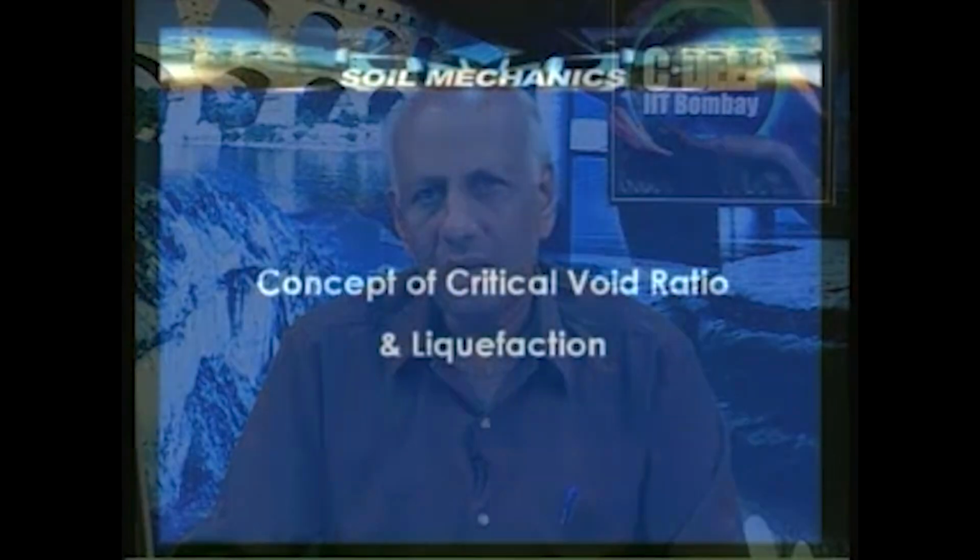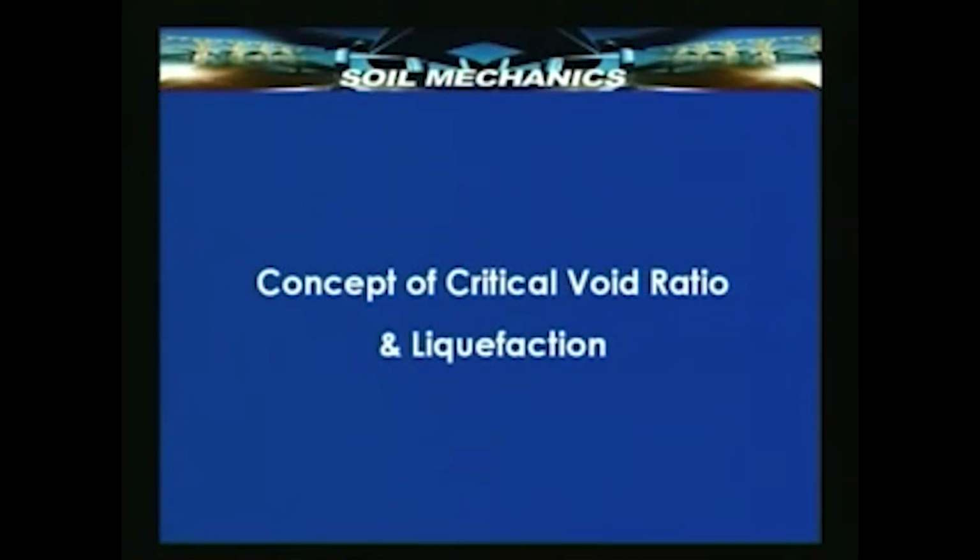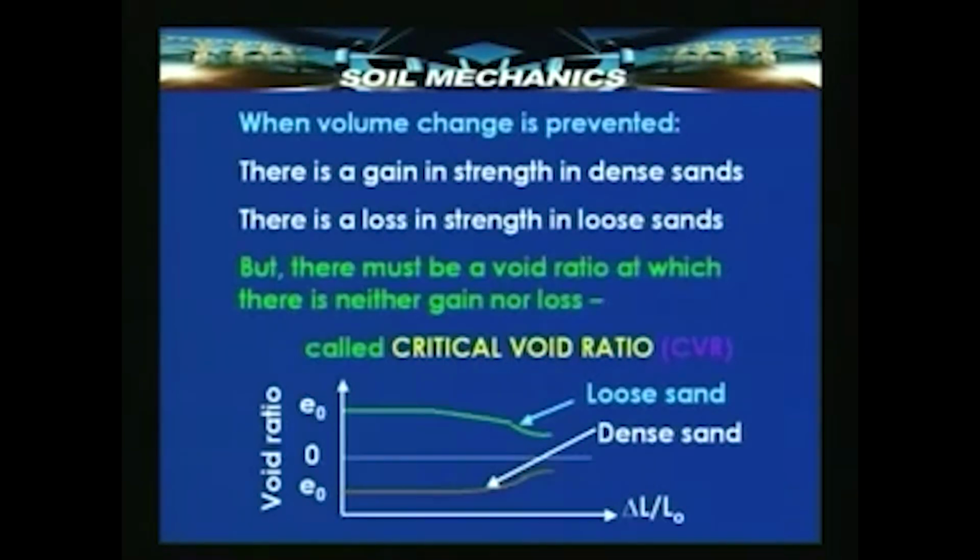Now let us take a look at the concept of critical void ratio, the meaning and significance of liquefaction, and how to determine it. When volume change is prevented, there is a gain in strength in the dense sands, because as we have seen in the behavior of the dense sand, there is a compression initially, and if volume change is prevented, this compression does not take place, and therefore there is a gain in strength.